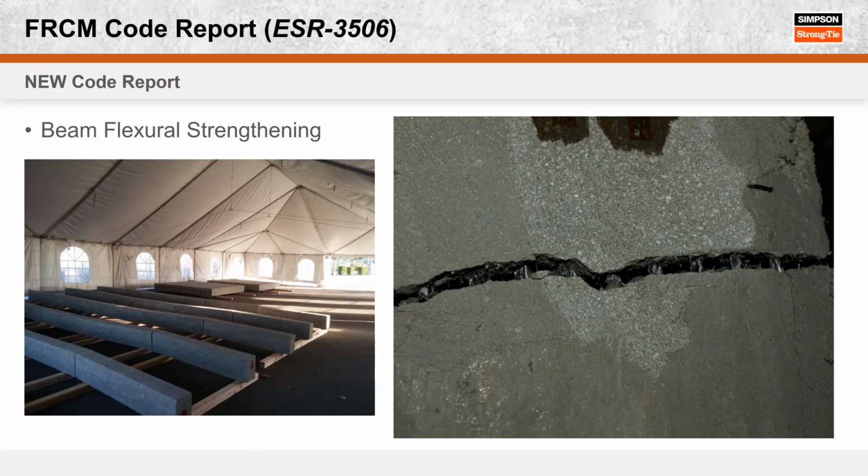But so you said for the surface preparation, a lot of people use a mechanical grinder. I think we showed you pictures of those before, we grind the concrete surface before applying the FRP. But that's a lot of manual labor.